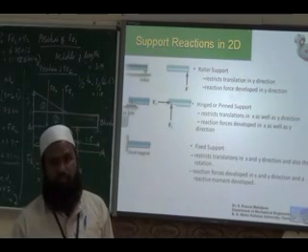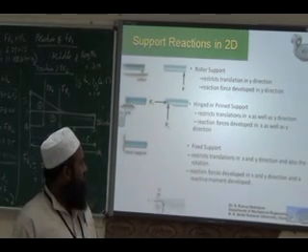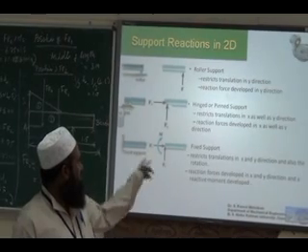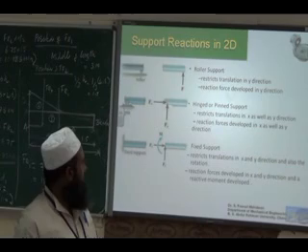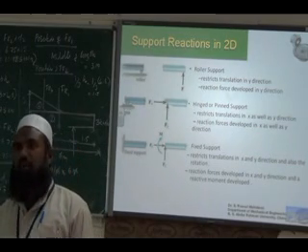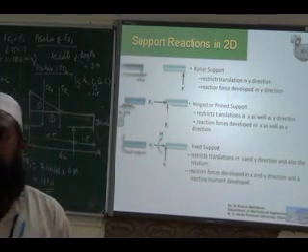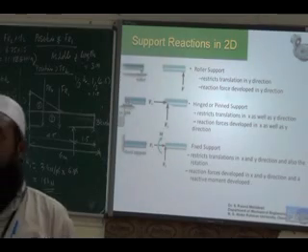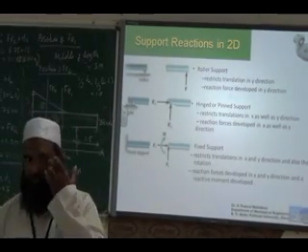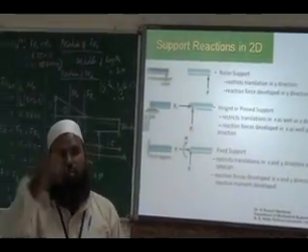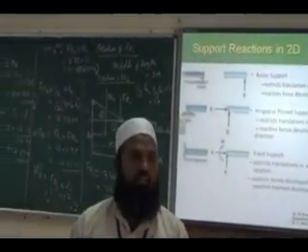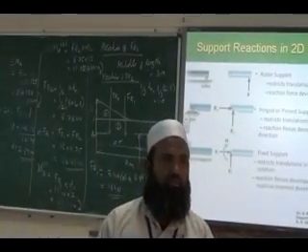So it restricts the translation in X and Y direction, and also no rotation around Z direction. The sign convention is arbitrary. At present we put it upward or downward. It depends on the way it is being moved or applied. So we just say moment is developed. Whether it is upward or downward, that we can decide only later, depending on the nature of the force we have.